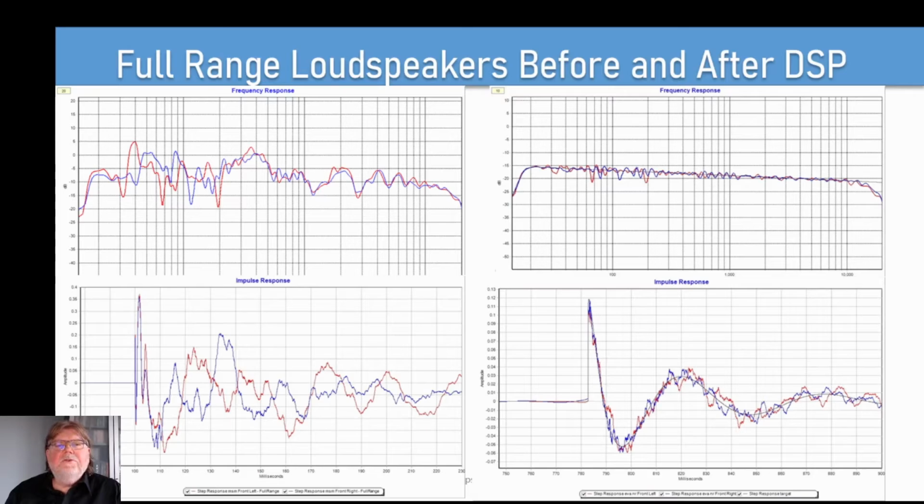Same goes for the frequency response. The key to getting an excellent stereo phantom center image is to ensure that the frequency response of the left and right channel are as near identical as possible. Otherwise, you get what is called phantom center image drift, that is frequency dependent. So at that frequency or range of frequencies, the image shifts towards one side and can go from side to side as frequency increases, for example. This is especially bad for center image vocals or lead instruments, or even bass guitar can sound off-center.